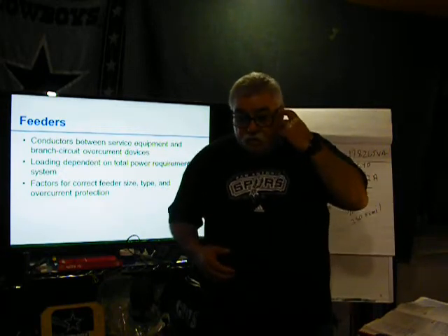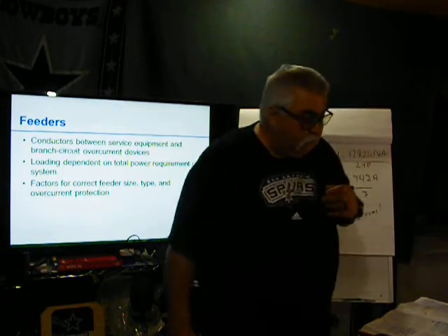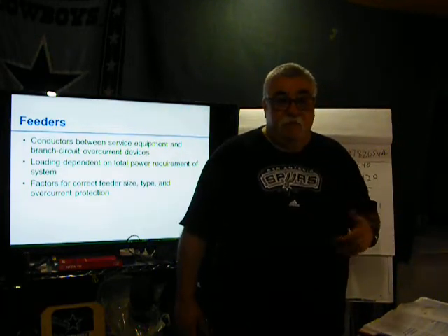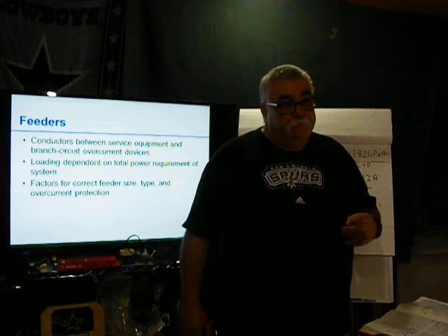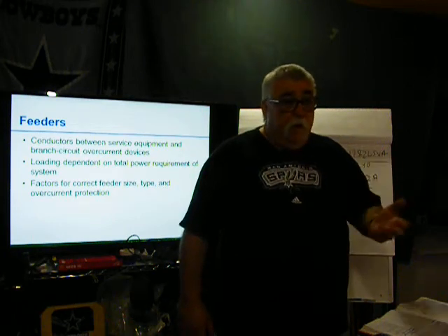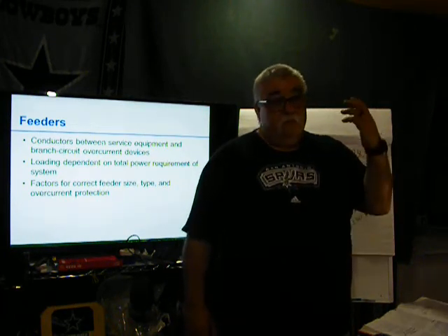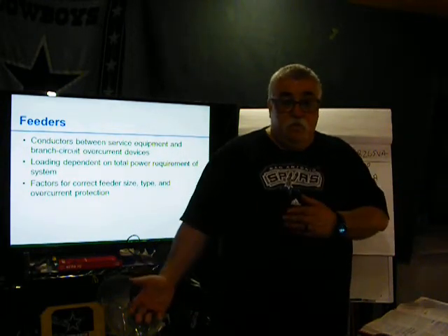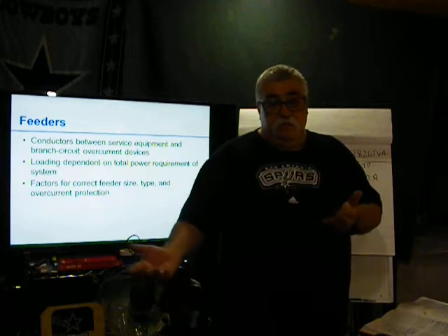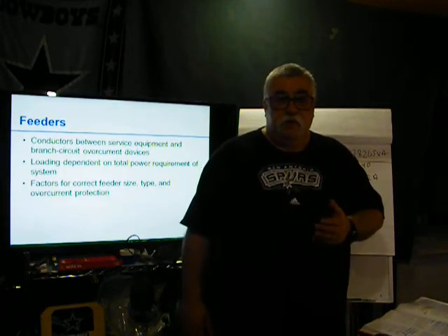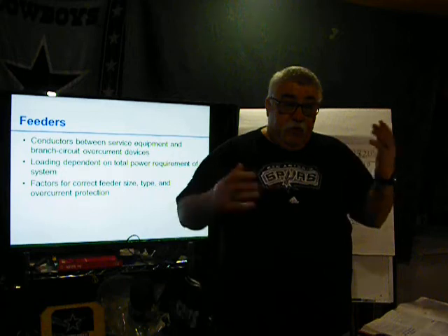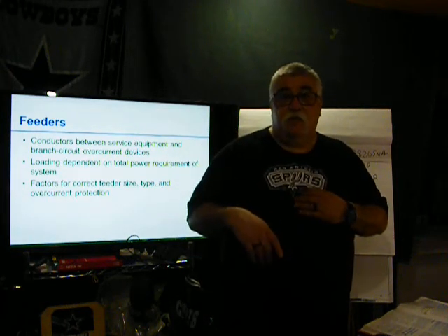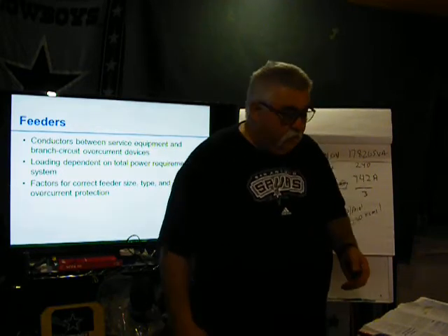Like when I worked in the slaughterhouse, meat packing place, they killed 1,500 to 2,500 pigs a day. All our conduit was aluminum. Why? Well, some of them, because they use water to clean everything down, and the others were coolers. So the average was around 42 degrees. You can't have condensation build up on these conduits. These conduits get rusted and then it gets on the meat. So that's why we used aluminum. Aluminum doesn't rust.